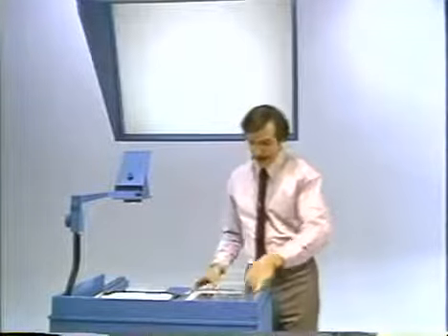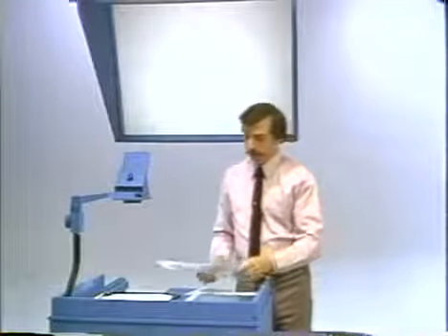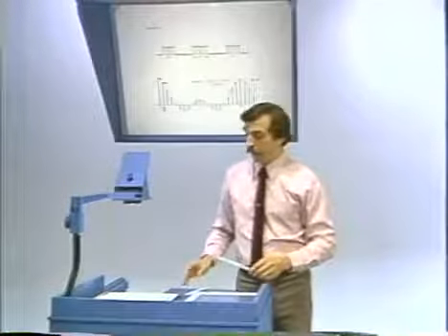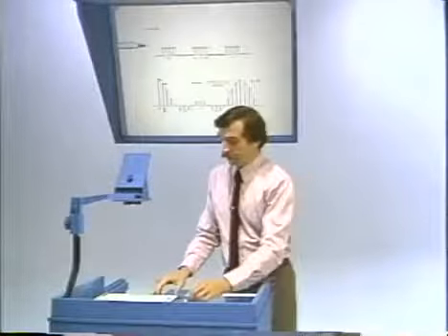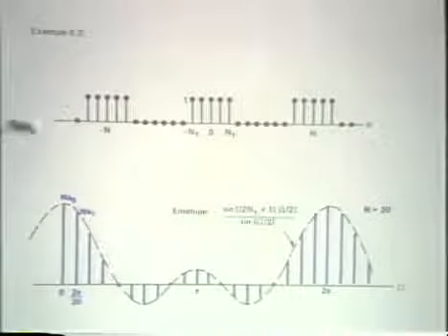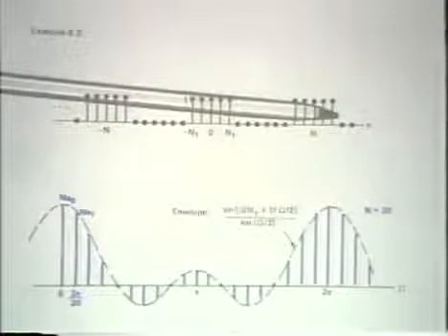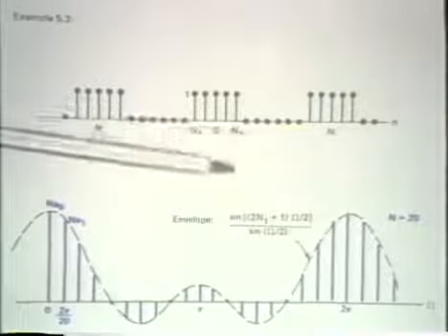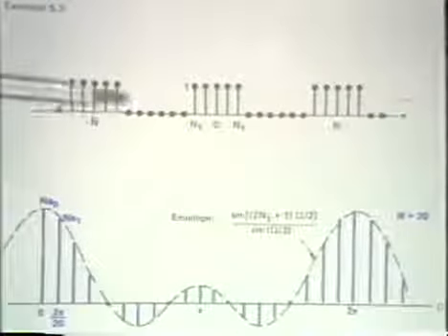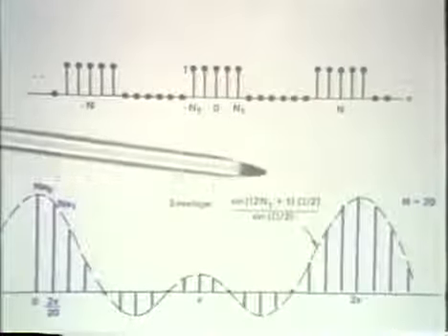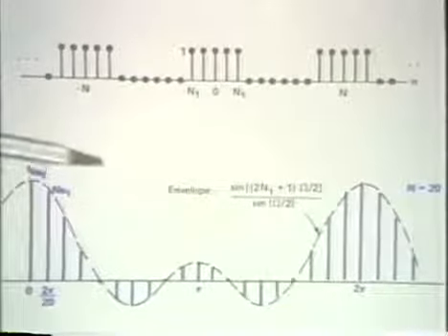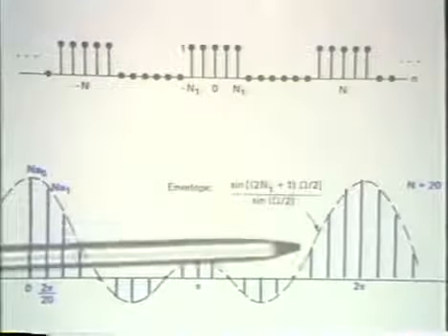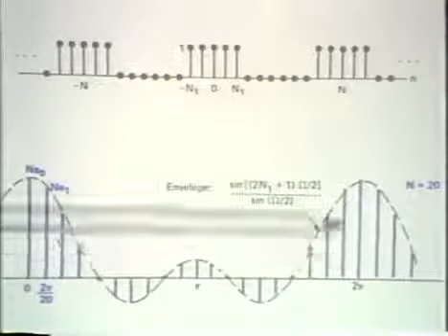And of course, we saw this in the context of our square wave example. In the square wave example, we have a periodic signal, which is a periodic square wave, and the Fourier transform of one period, in fact, represents the envelope, and here we have the envelope function, which represents the envelope of the Fourier series coefficients, and the Fourier series coefficients are samples.